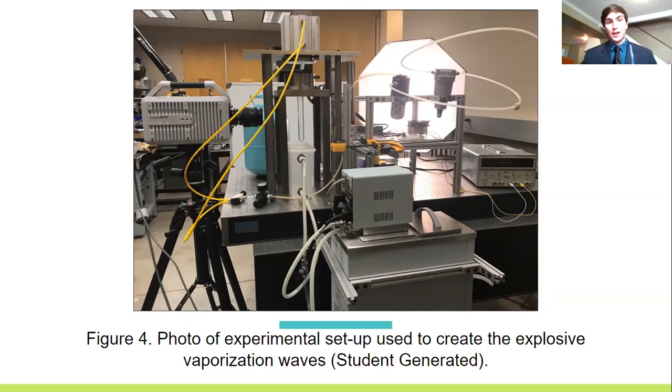After this is sealed off, what I do is I take the refrigerant R134A and connect it to the test tube environment. And the reason why R134A is used is because it actually has a very low boiling point. Its boiling point is below room temperature. So once it meets room temperature, it's going to immediately boil. So once that pressure is released, it reaches room temperature and goes through this rapid boiling process, which is what I want to simulate with this experiment.